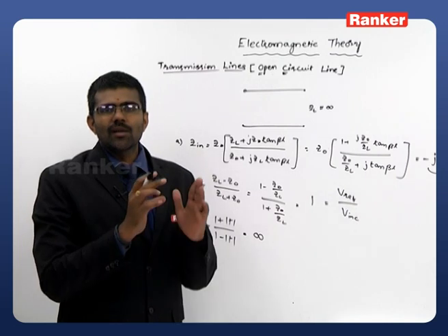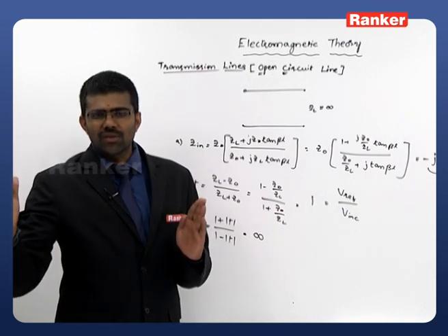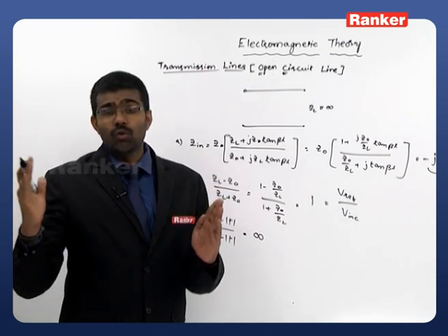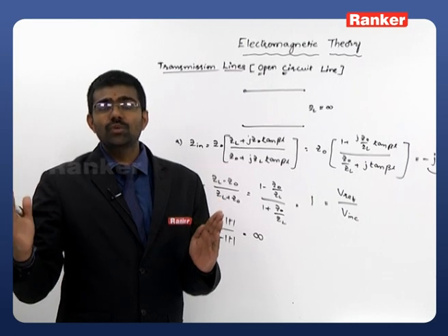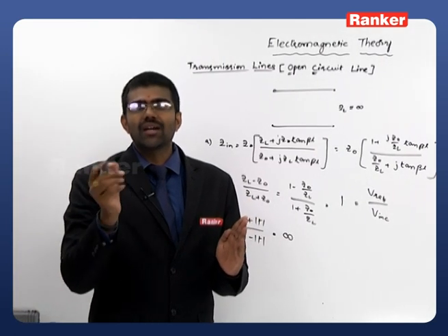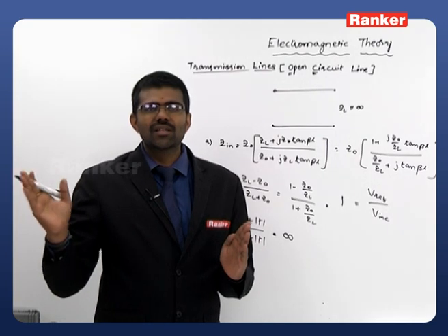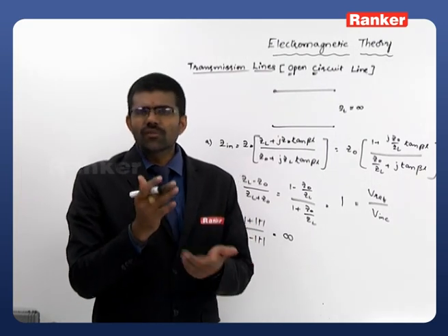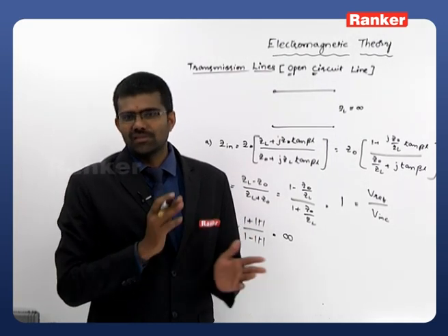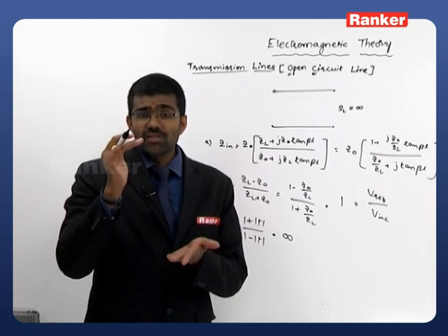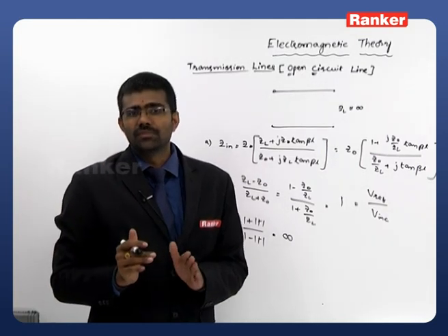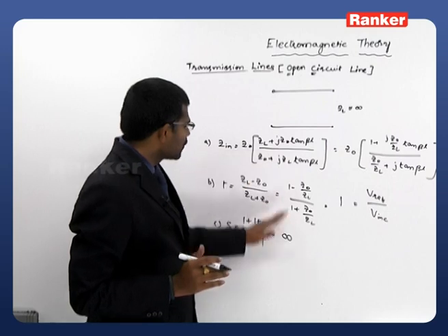Whenever the signal is applied and the output is short circuited, or the signal is applied and the output is open circuited, in these two cases you are not getting anything from the output. The complete signal will be reflected, with phase shift or without phase shift, which purely depends upon the case, right? And the maximum voltage standing wave ratio can be observed. Now this is the case that we have.